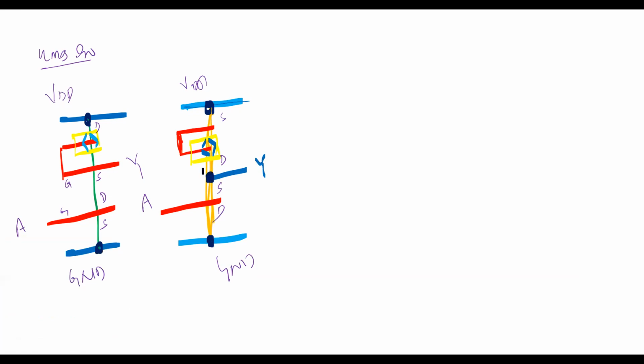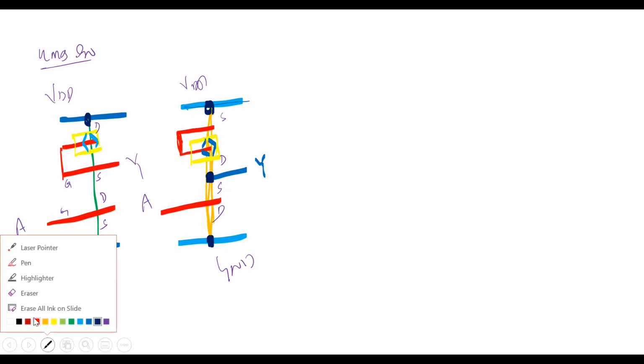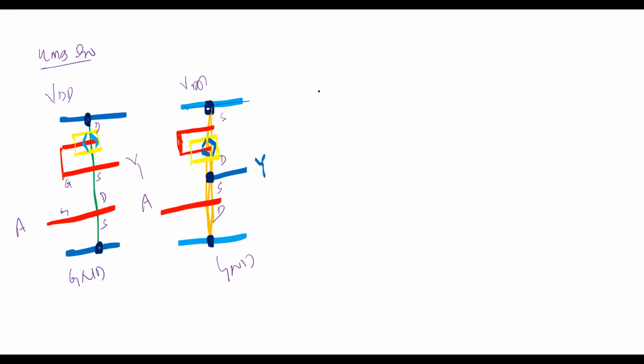And one more thing is CMOS. You know about the CMOS. The CMOS inverter circuit is different. As we know, the CMOS inverter circuit is this one. So one PMOS and one NMOS should be there in the circuit; both should be equal in number. VDD. So this is the PMOS transistor. This is the NMOS transistor. Both the gates are joined together and give the input A, and the output is connected here.